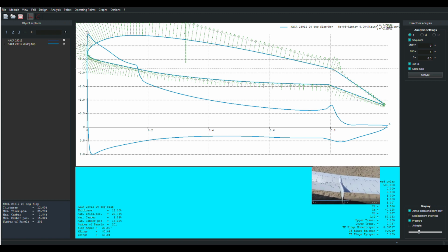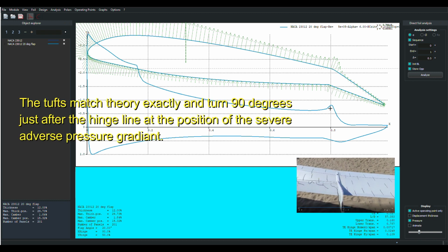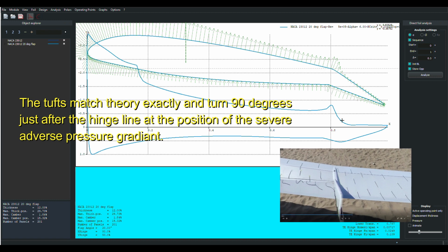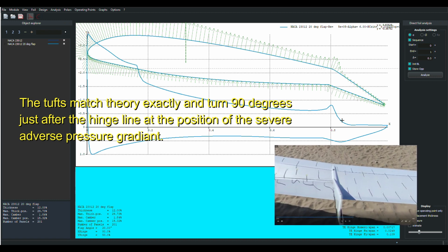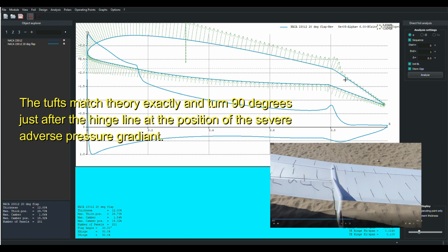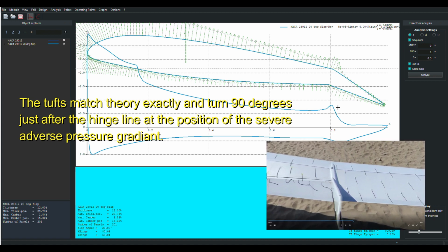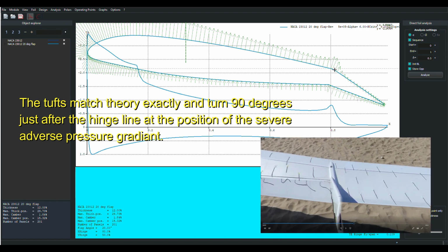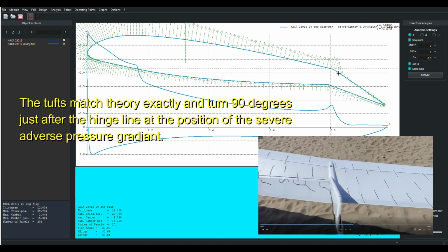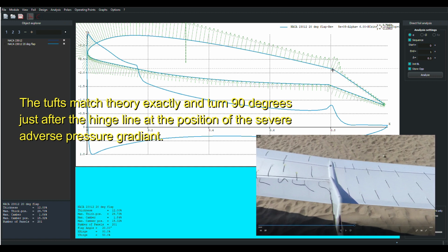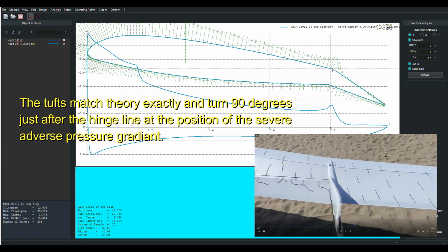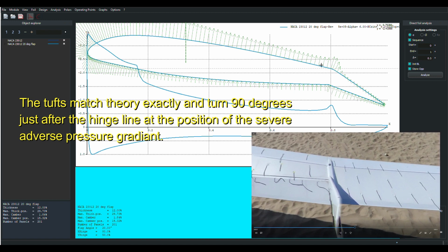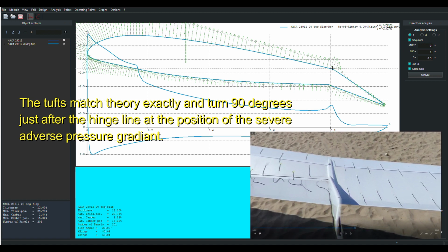And then bam, they run into a wall. Literally, we've created a wall here for them. You can't see it. That's why it's not the first thing we thought of when we had problems. But by having this type of control surface, you build a pressure wall here. This adverse pressure gradient here is tremendous. And it's way back where a lot of the energy that was in the boundary layer has already been spent beating its way into the adverse pressure gradient. So it's made it really hard here all of a sudden.